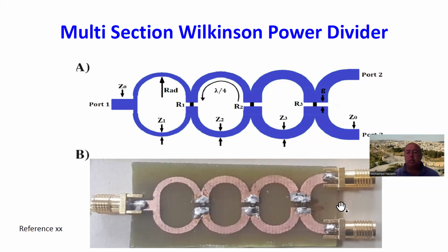And here's an example of how the layout basically comes together. You come up with this artwork where these are quarter wavelength sections, and you can see we started out with narrow width lines, meaning high impedance lines, all the way to near 50 ohm. In this case, these are 50 ohm in here, but this one here is a near 50 ohm line, okay?